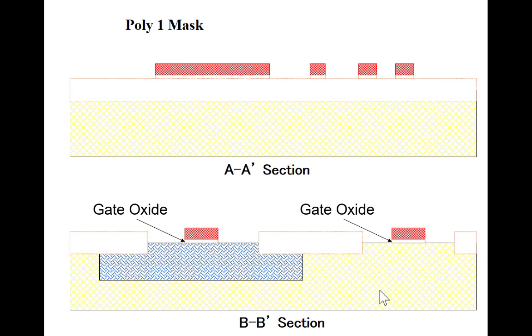And if we did, we could probably change the threshold voltage of the devices. Is there an advantage for doing it at the same time? Cheaper. One processing step gets them both at the same time. And for some circuits, there's an advantage of having a match as well. When we do it at the same time in most processes.